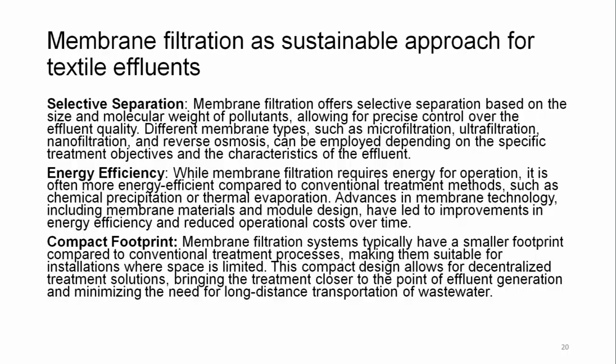Selective separation. Membrane filtration offers selective separation based on the size and molecular weight of pollutants, allowing for precise control over the effluent quality. Different membrane types such as microfiltration, ultrafiltration, nanofiltration and reverse osmosis can be employed depending on the specific treatment objectives and the characteristics of effluent.